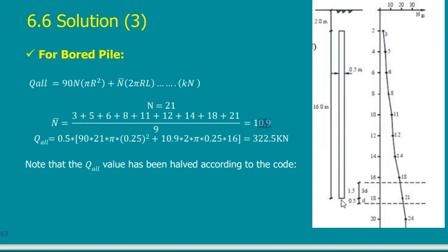But it will be a very strange coincidence that at this point I have a value. I may have a value above or sometimes below. So they tell me in this equation, from the pile tip, go below 1 pile diameter, and go up 3 pile diameters. And any values in between these dotted lines, take the average of them.